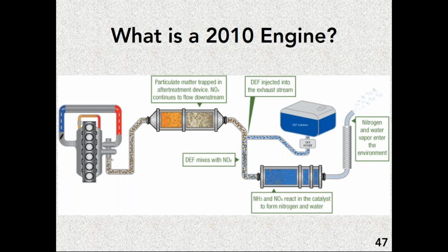So that's where something called DEF, or diesel exhaust fluid, comes in. Diesel exhaust fluid is in the tank right above the SCR system. And in the exhaust between the diesel particulate filter and that selective catalytic reduction system is an injection point where some of this DEF is injected into the exhaust. Now, DEF fluid is actually urea, and urea is a high nitrogen component or chemical that when you expose it to the right temperature of heat, it actually converts nearly 100% to ammonia.